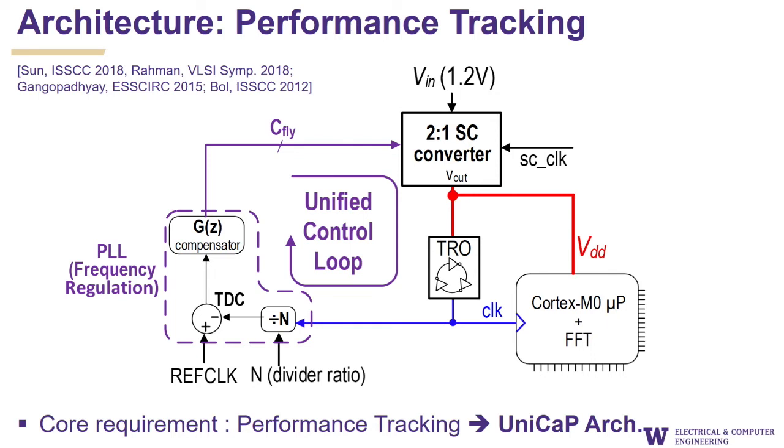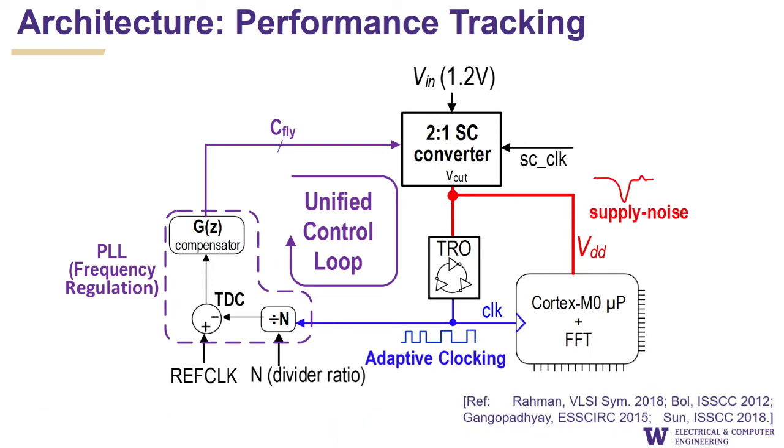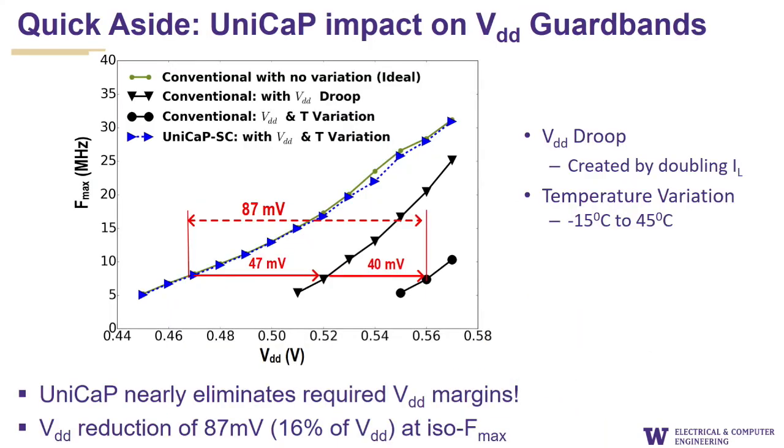and the basic trick to that is to build a PLL, but having the PLL absorb the voltage regulator. So we're literally merging two traditionally disparate fields, voltage regulation and PLL design, into one combined system, and that sort of fusion gets you this unprecedented capability for margin removal, right? But that's a completely different piece of work, so I won't go into that. You basically run in performance lock using Unicap,